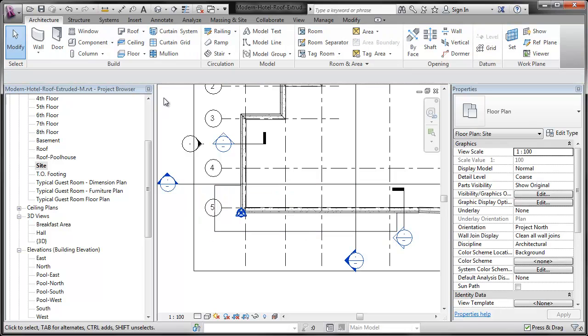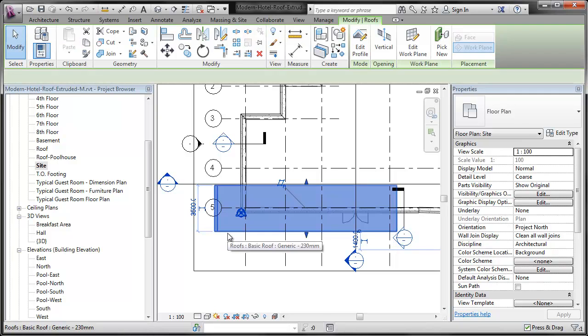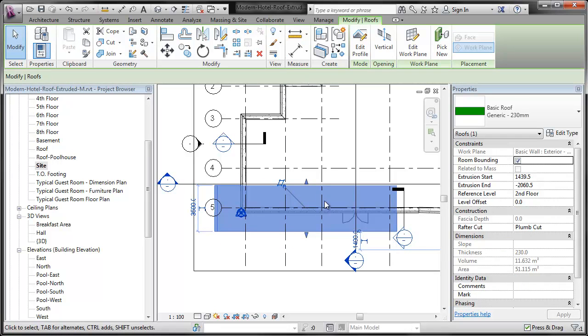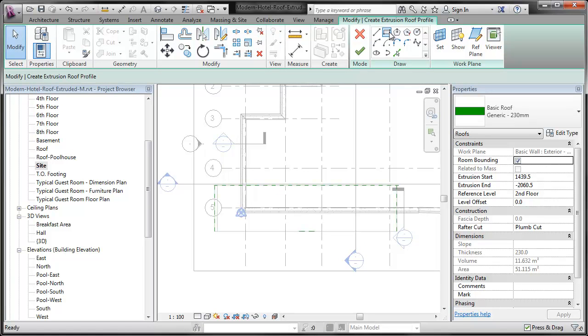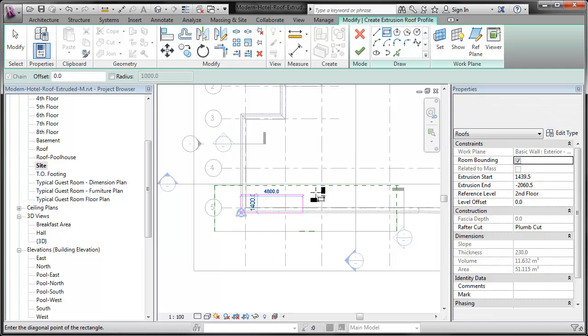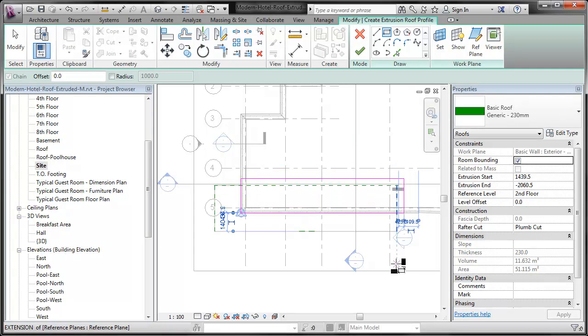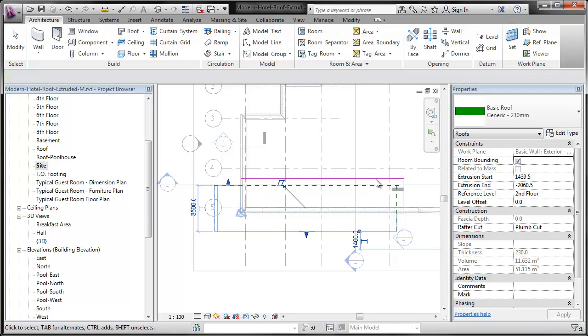So what we can do is go to the Architecture tab, over to the Openings tab, we select the roof, and once we select the roof we then say we want a vertical opening, and then the roof itself is a little bit green outlined, and then we can draw a little opening around the roof, which will be the area that will be chopped out. We can then go finish.